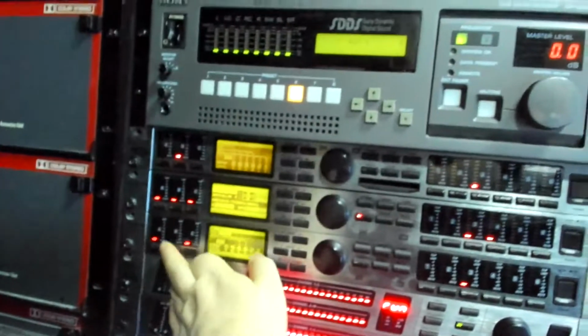It sounds like it's got a tone that's there, but it's very low, of course, in sound pressure level, and I dare not play it too loud. And of course, I've got the crossover frequency on the DCX set at, presently, I'm experimenting down at 254 hertz, Linkwitz-Riley 24 dB per octave. So it's like it is on the DCX.